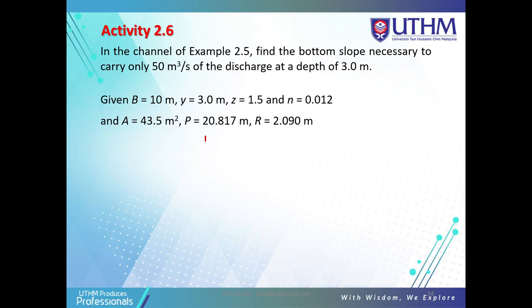The Q, so you must use the Manning here. Q is equal to A times V, where V is (1/N) A R to the power 2/3 times S naught to the power 1/2.